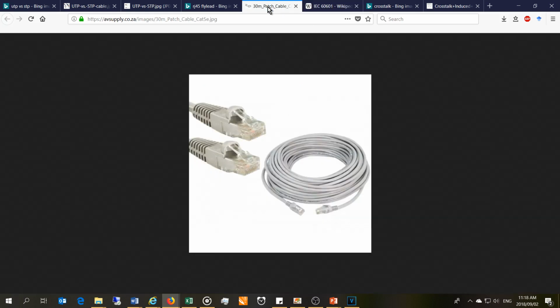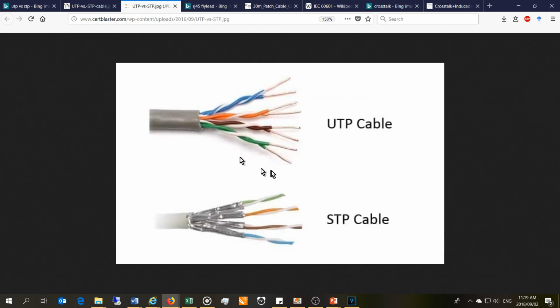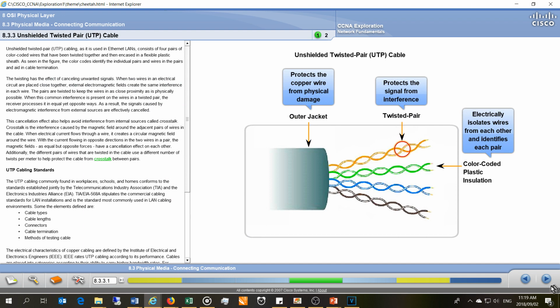So if, for example, this cable had gone hot, or some supply cable had cut in here, or somebody had shorted this out to a supply cable, to stop the patient lying in the hospital bed from getting a shock, or the patient monitor, the monitoring device, from having a fault, it will then be brought to ground because of the shield that was sitting over here. All right, getting back to the notes.